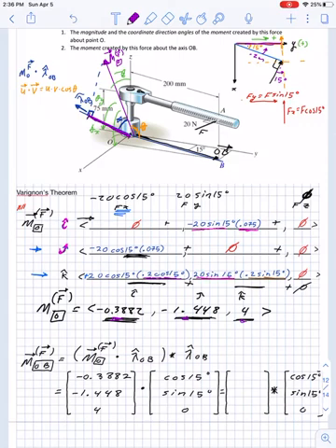But it's just a value. It just gives us the length of this, right? But if we want to find the moment as a vector, what do we do? Well, if we just have a magnitude, don't we only have to multiply by the direction? And that direction is lambda OB again. So that's where we have the moment down here, dotted with the unit vector lambda OB.